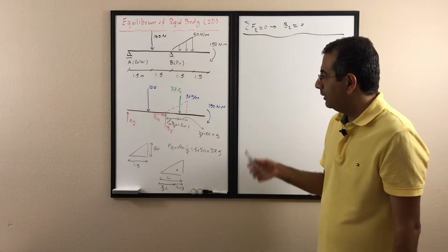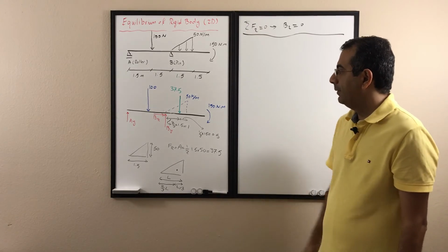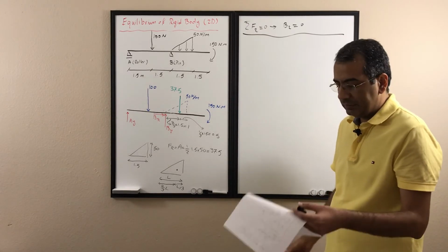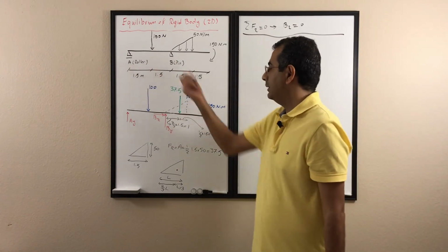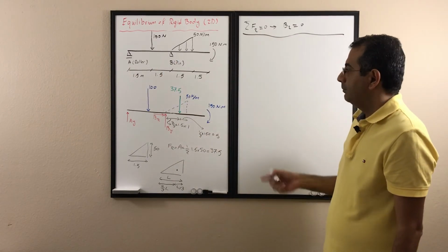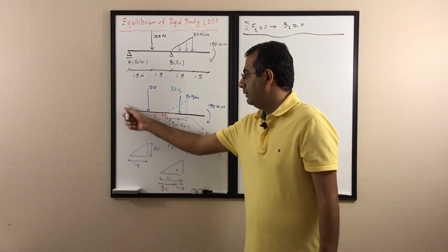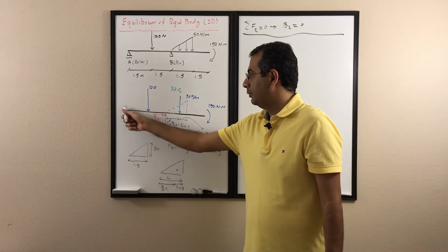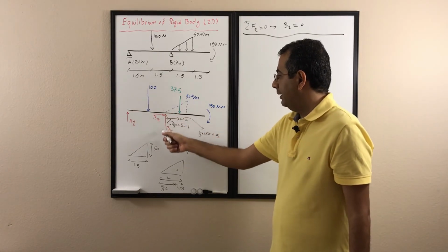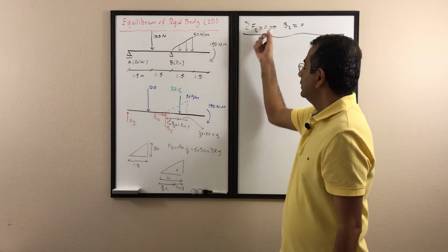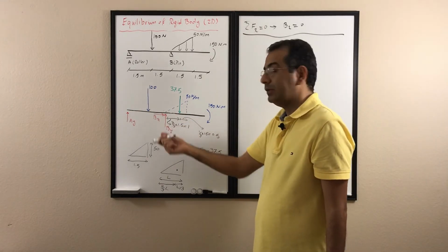So it's better to go ahead and find and use the moment instead of using the Fy. So the moment, again, I can use the moment about point A or about point B. Either of them works. If I write it about point A, the moment of Ay about point A would be 0, so Ay would be eliminated from my equation. And Bx is also 0, because it also passes through point A. So the moment of Bx is also 0.